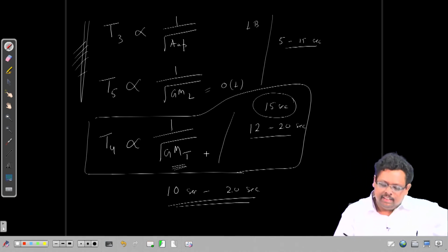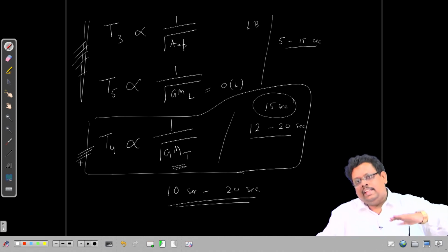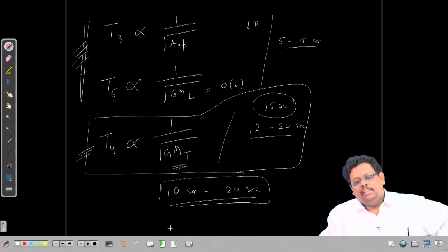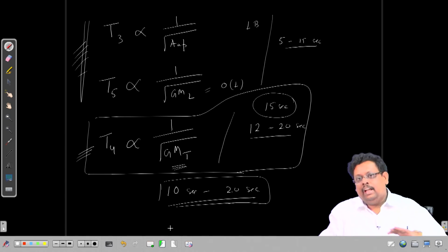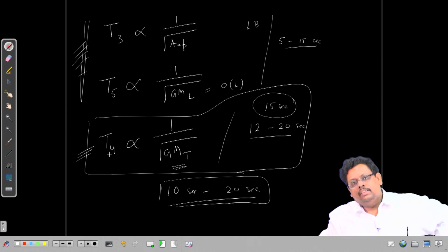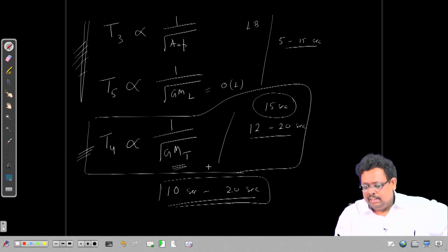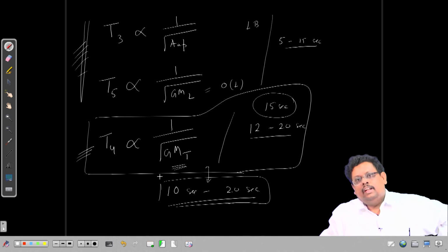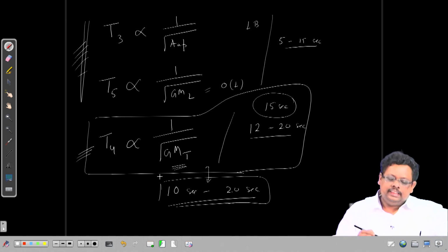Now, you can see that it is very much possible that the roll natural time period falls within the range of these so called regular waves. So, therefore, in the ocean we have to be very careful about the capsizing of the vessel, especially we have to take care about the roll, and also because of this we have huge discomfort to the passengers, because sometimes if we start oscillating in some resonating mode, with waves hitting close to the natural time period of the roll, then the passengers face a lot of uncomfortable situations. Some people vomit also, you can call this sea sickness, right.